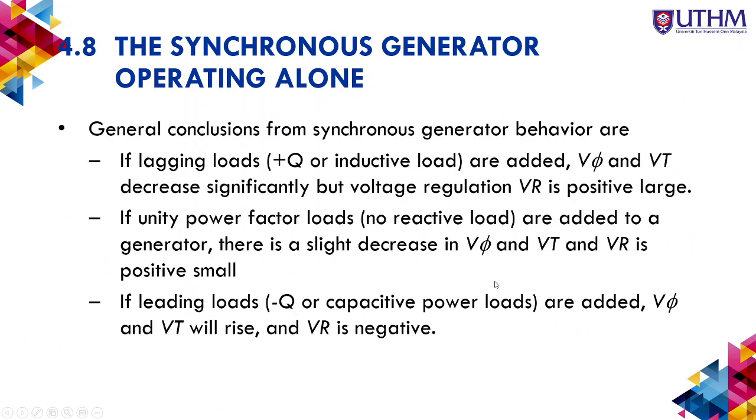In conclusion, if we increase lagging loads, V phase and VT will decrease significantly, and the voltage regulation will be positive with a large value.